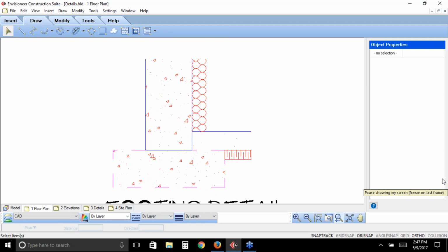If I wanted to adjust that to be twice as big, because this is a 1/2 inch detail, instead of saying I wanted it 4 inches thick, I should have said 8 inches thick, and that would have made it bigger. But when you're working on the drawing sheet, and I'm not working inside the detail, I inserted that as a separate entity, it's looking at my overall scale in my drawing sheet, and that is 1/4 inch equals a foot.